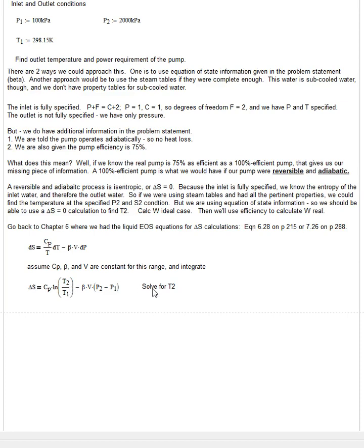All right. If you think about this, when we solve for the work, what are we actually solving for? I didn't write this down, but I'll write it right here. Work for the ideal case is equal to what? This is just the first law. That's going to be delta H for the ideal case, or for the isentropic case. So work isentropic or work ideal is the same. They're the same thing. That's equal to delta H.